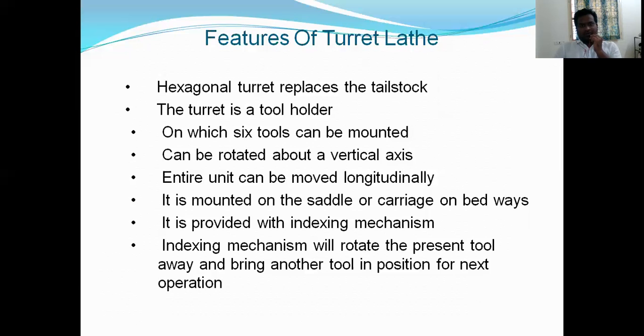If we are doing the drilling operation at present, after that we are going to do the boring operation. So for that reason, we operate this indexing mechanism. This indexing mechanism will rotate the present tool away, exactly by some angle. Indexing means it is rotated by angles.